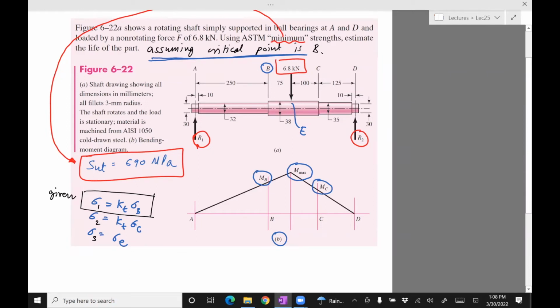Yeah, there will be. In this case, you will be able to do this with finite element. The only issue is that whenever there is stress concentration, finite element has problems because the stresses grow very quickly, and then the question is how small a finite element you need in order to capture that stress.